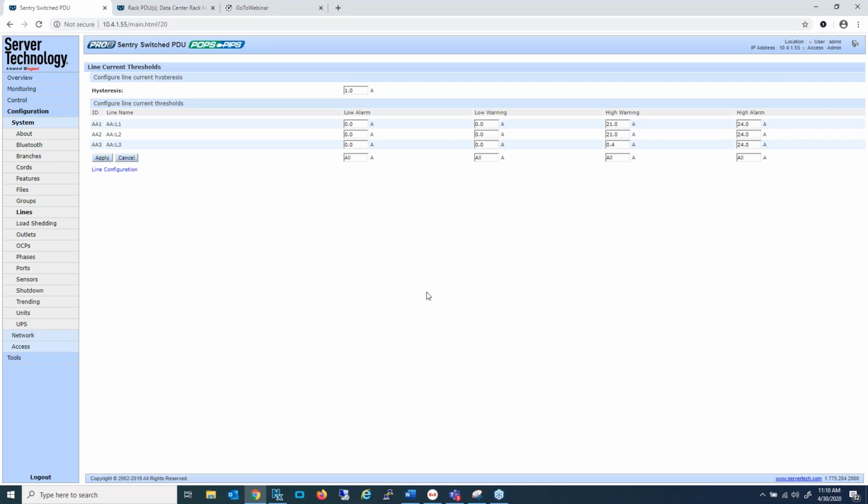That is, you would consider changing the high alarm down to 12 amps and the high warning to 10.5 amps. That is for the contingency that if one of the 2 PDUs were to be powered off, either intentionally or during maintenance, the failover current to the remaining live PDU would still be well under 24 amps, and you would not be in a territory where you're jeopardizing tripping the upstream circuit breaker.